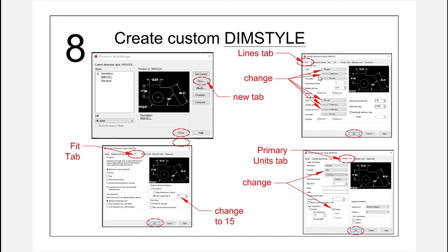After you have the new style, it should open. Use the first tab, the Lines tab, and we change the color to ByLayer. Okay, we change the linetype to Continuous. We change the lineweight to ByLayer also. The lines, this is ByLayer, then Continuous, then okay.